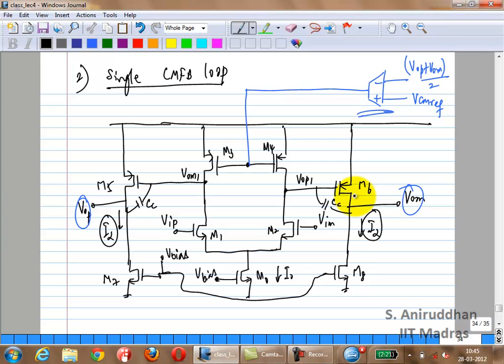So if you go through the common mode feedback loop, what are the dominant capacitances as you have it right now? What is the dominant node right now? M3, M4? Well, I would think it's VOM1 and VOP1, because you have a huge Miller capacitance there already because you have compensated your differential mode. And that also appears in the common mode. So there is a possibility of making CC the common compensation capacitance for both the differential loop and the common mode loop because it is a common path. M5, M6 are common to both, correct?